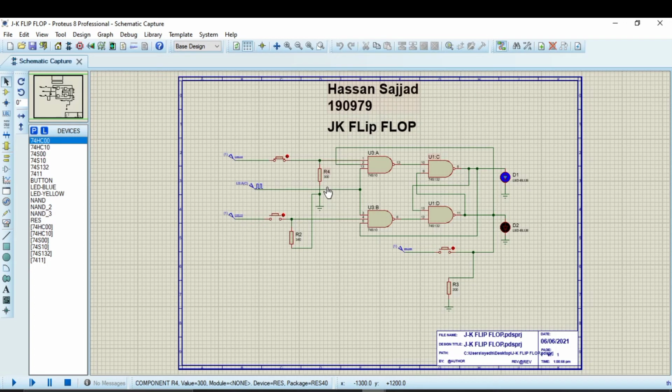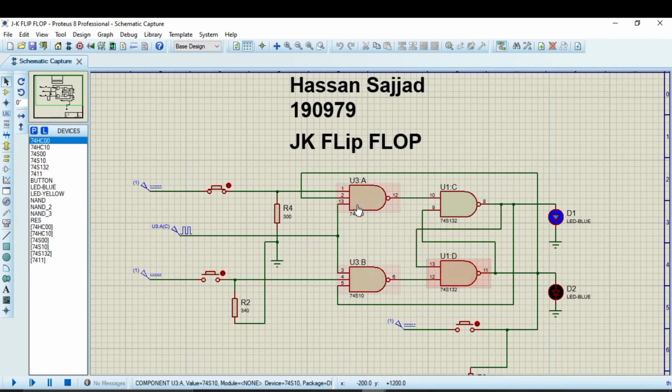So here is the entire structure for the JK flip-flop. It is similar to the D flip-flop, but here is the input at D2, and this input is connected with the 3-terminal NAND gate. You will see that the resistors are just used to ground the input, and the voltage drop will appear at the NAND gate, 1 terminal out of 3. The clock is provided to each of the AND gates, which work as an enabler. So here we go.